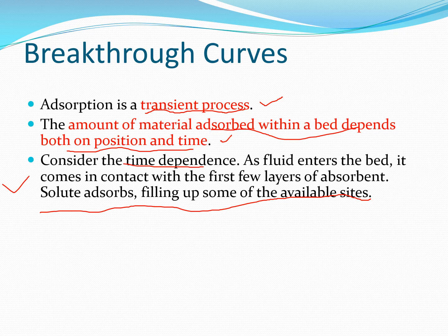Now adsorption started, and the feed stream is contacted with the first layer of the adsorption bed. After a certain time, like 10 minutes, 20 minutes, whatever time is set, that area will be saturated and adsorption will move further along the length of the bed, until the feed stream exits the column.